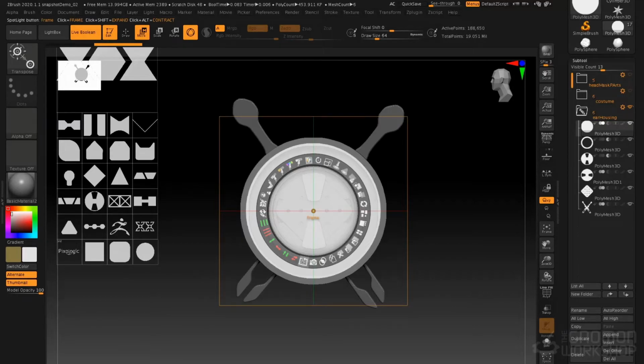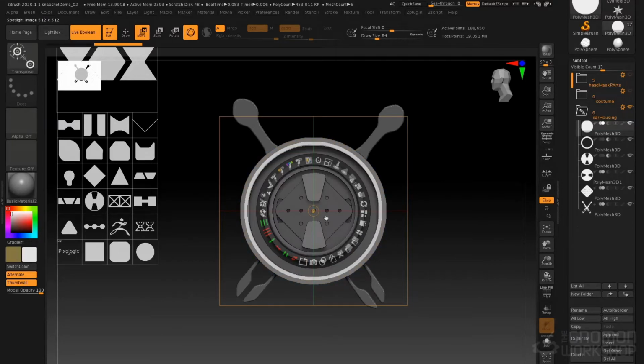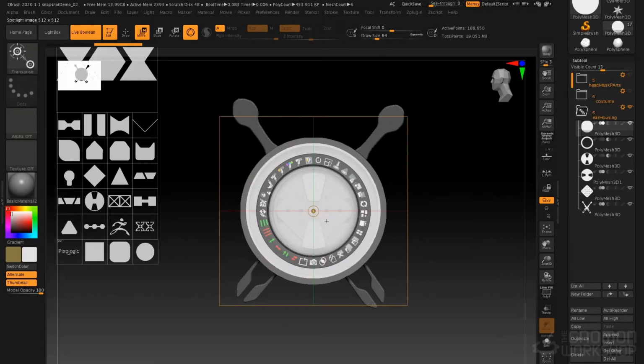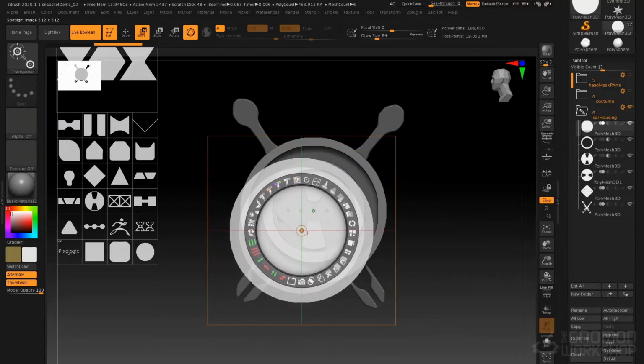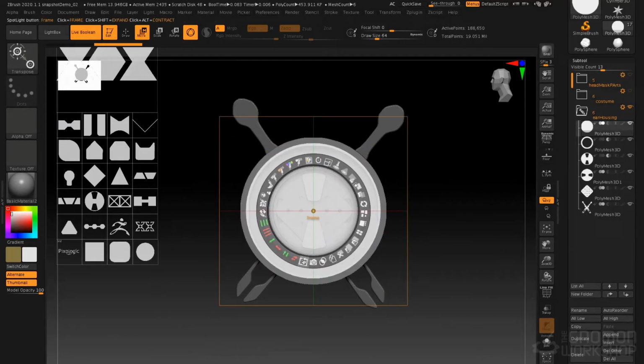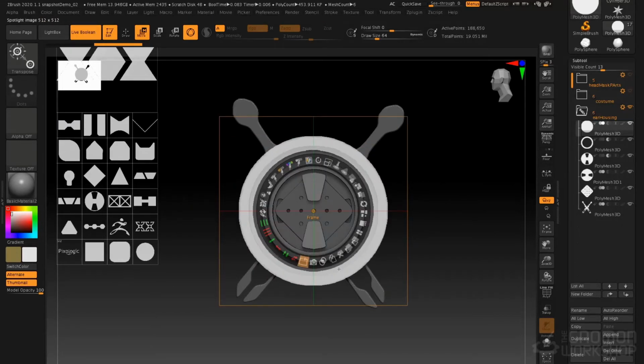Now, again, if I Alt click drag frame, it will contract it like that. So it does something along those lines. If we undo that and go back to our frame mode here, clicking it will just frame. Shift click will expand it like that, as you can see there. So I am going to undo that, and I am just going to do my regular frame like this. And I'm going to make that a subtraction object by alt-clicking.